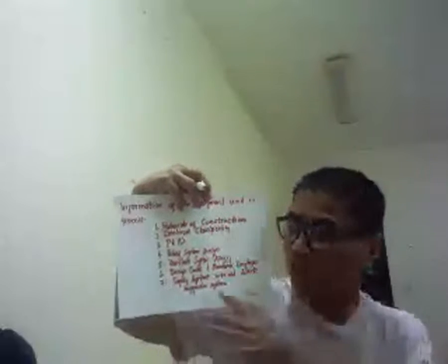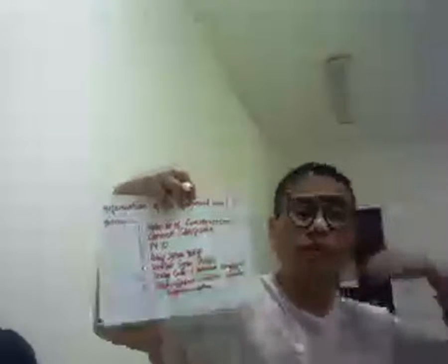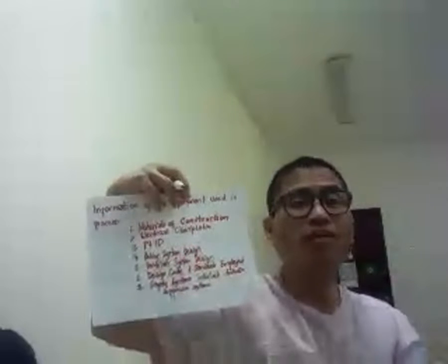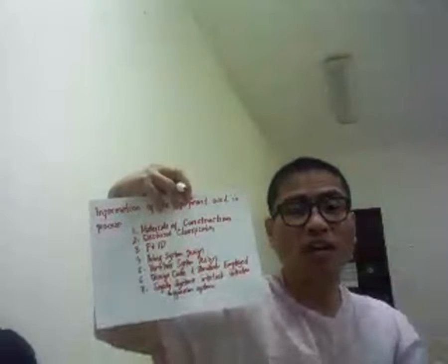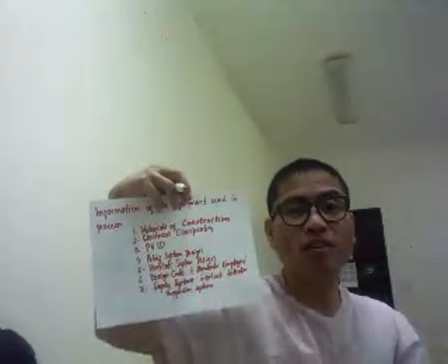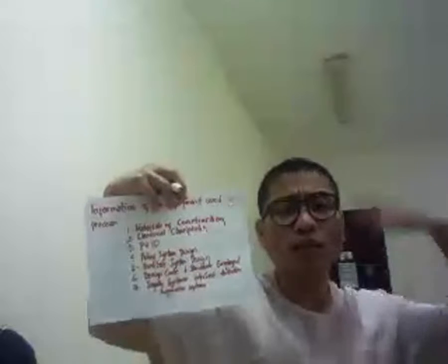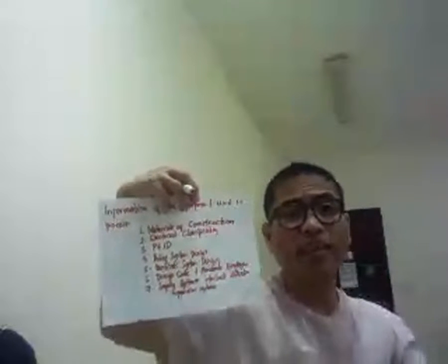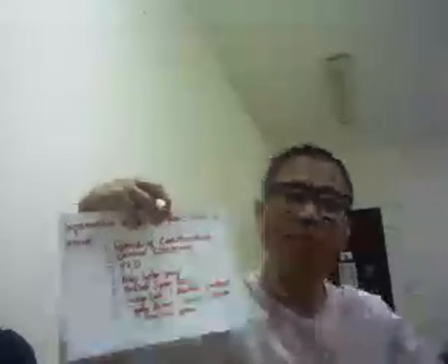So this applies here, safety system or other safety devices, not only for leakages, abnormalities also. For example, if the level of the tank, say you are producing liquid products, and the liquid is too high so it becomes full, then it will signal also, an alarm, automatic, and then it will be adjusted to the appropriate level.